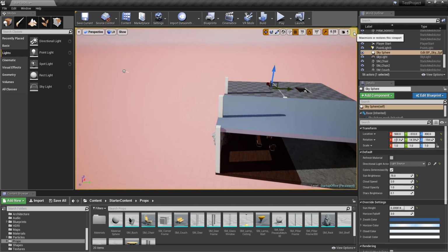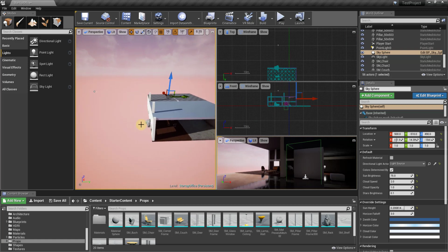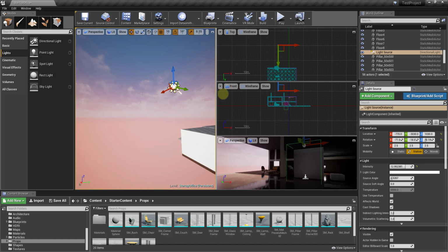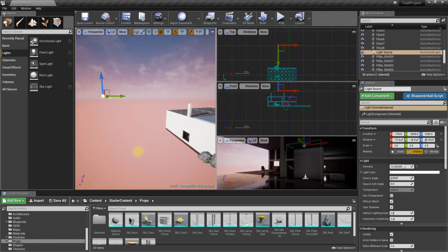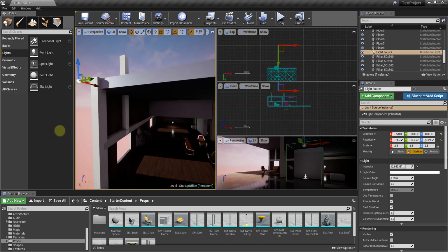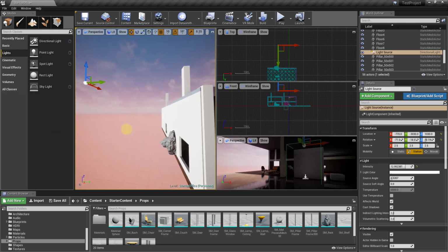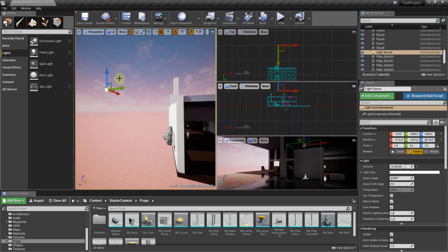What I'm going to do in this case is I'm going to go to my kind of windowed mode so that we can take a look at this and you can see what's changing. And so in this case, if I was to click on this directional light item, I can come in here and if I fly into it and I look at it, you can see how right now it's set up with this little arrow coming off of it. Well, the little arrow right here is indicating what direction the light is shining. And so what that's doing is that's affecting the shadows that are being cast. So right now this light is shining through these windows, casting these shadows. Well, you can adjust the way that that works within Unreal Engine by moving and changing that light around.